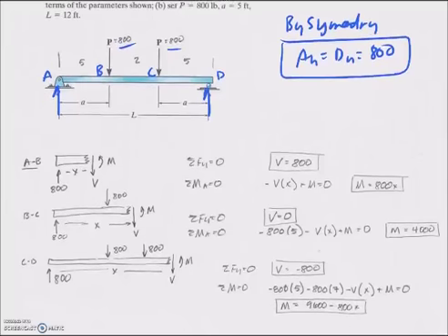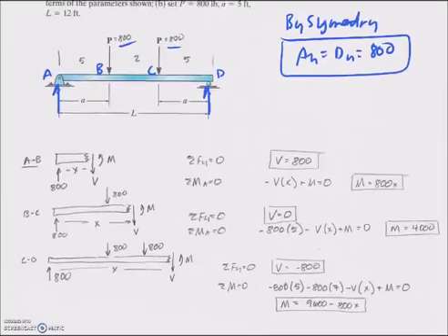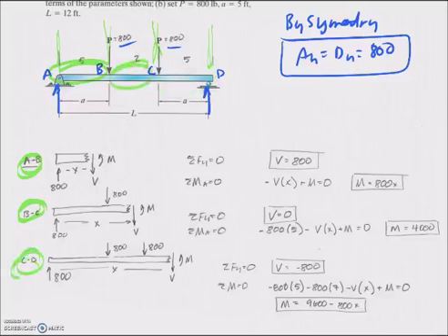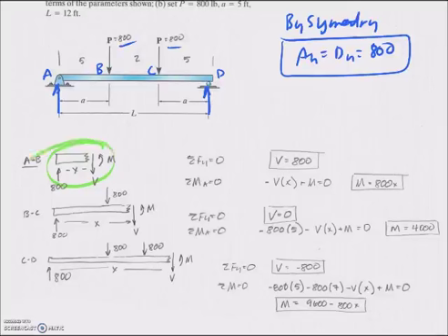All right, I'm going to shortcut the process just a little bit, focus on the shear and moment graphs, but what you do is recognize again that there is a discontinuity that happens between these applied forces, and you have to have a separate set of equations that applies here. So I need a set of equations that applies between A and B, a set between B and C, and a set between C and D. And so I do all that by drawing a squiggle line first, and then drawing a section, drawing a free body diagram of the section, and writing all the equations out. Then I do another one.